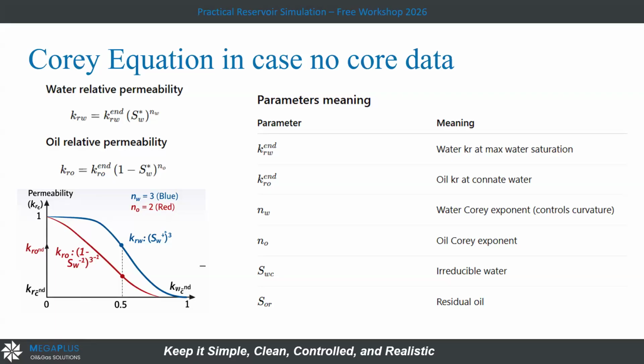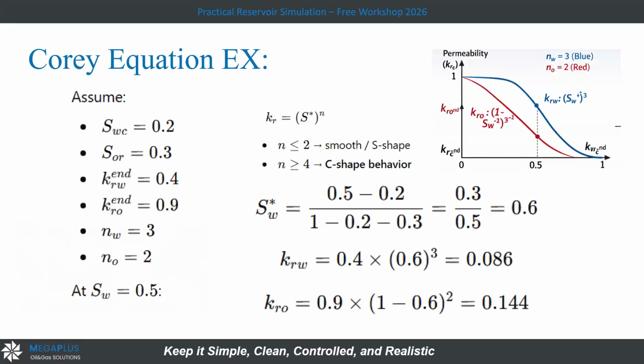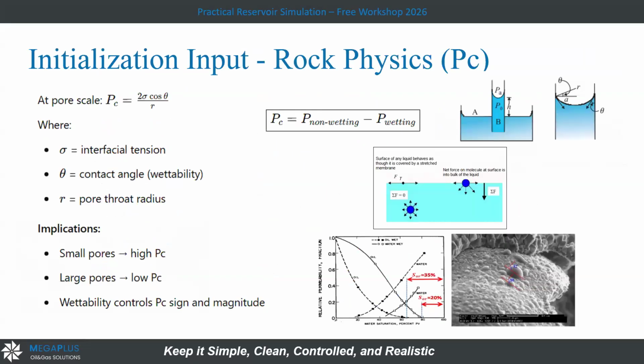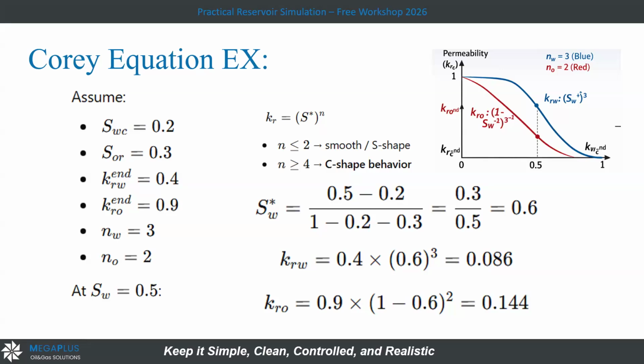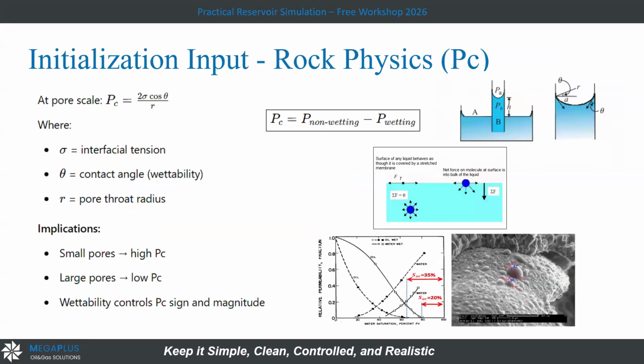We make our dynamic model understand the fluid flow behavior with change in water saturation, which is a function of pressure, described by the diffusivity equation that is converted to numerical form. This is exactly how it works. So this is about the relative permeability curves, and this is how the fluid is moving related to pressure and water saturation.